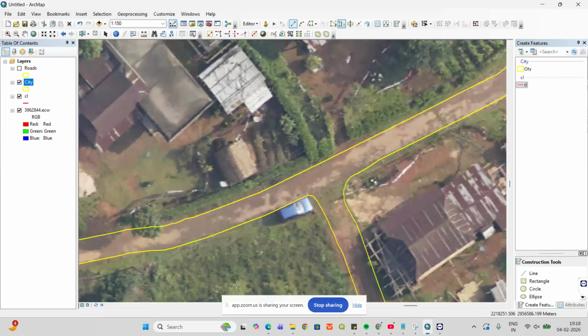Like 50% we can do ourselves, because GCP can be done irrespective of climate or weather. We have 10 to 12 equipment instruments, and per day you can cover some 4 to 5 square kilometers with it. Since we have 12 equipments, we need only two people per equipment, so we'll deploy 24 people.